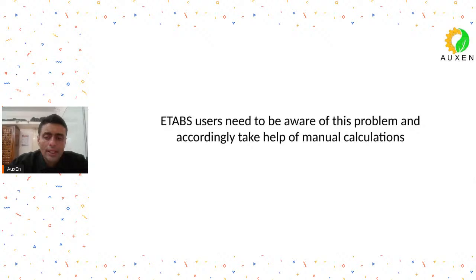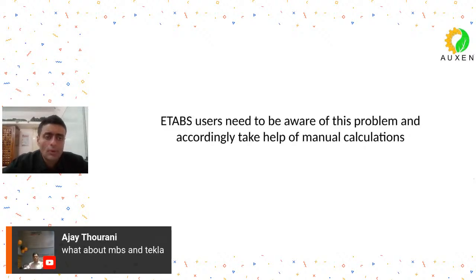Yes, someone was telling me that in the STAAD series also they are facing a similar problem. So I tried to check yesterday in STAAD, sorry, in Connect Edition, my mistake. Someone informed me that in STAAD Connect Edition also there are certain problems, especially with slender web cases. So those who are using STAAD.Pro Connect Edition can take a section where the web is becoming slender and try to cross-check the moment carrying capacity and load carrying capacity with manual calculations. Just try to do that.